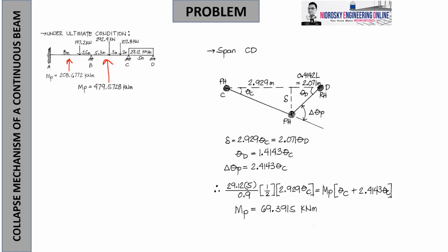Okay, already discussed before that we already derived that the point D is taken as a real hinge, no? Because it has no adjacent span and no interlocking moment. Again, in the presence of interlocking moment, as you know from theory of structures, there should be a plastic hinge. We are aware that at point D, it does not have an interlocking moment based on theory of structures principle. So, therefore, we can say that point D is a real hinge. And the rest, like at the point of hinging, and of course at the interior support at C, create plastic hinges.